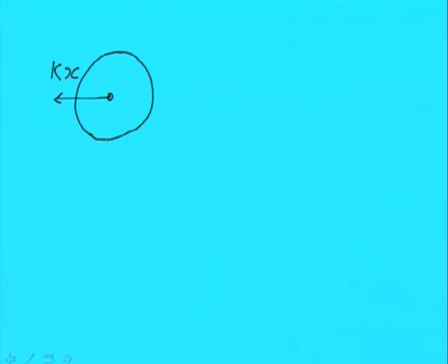So there has to be some friction force which is allowing the pure rolling motion to take place. So this is the friction force, and we know that this particular cylinder has theta rotation, but the linear displacement in this direction is x.